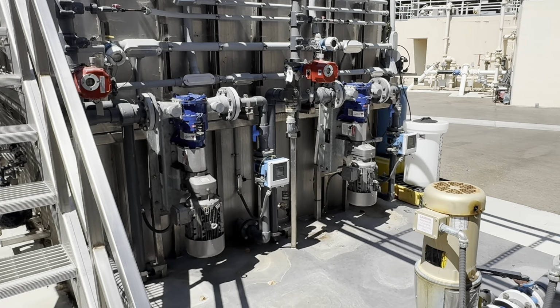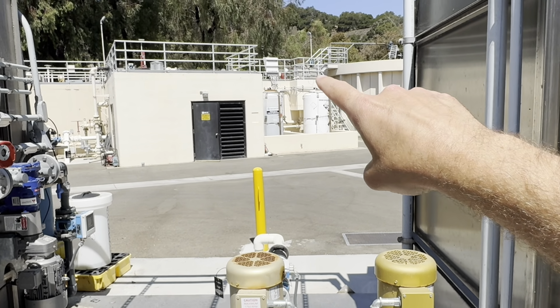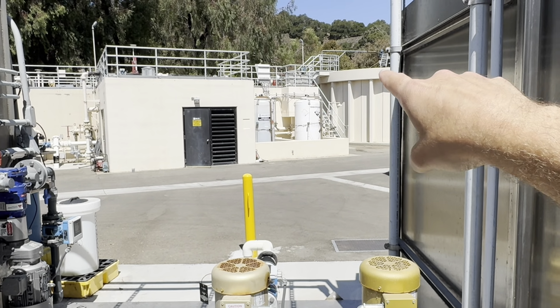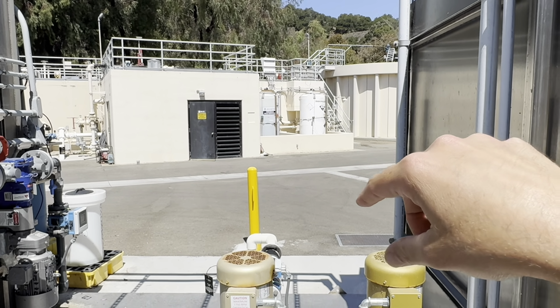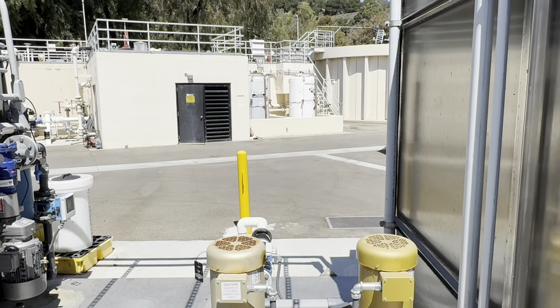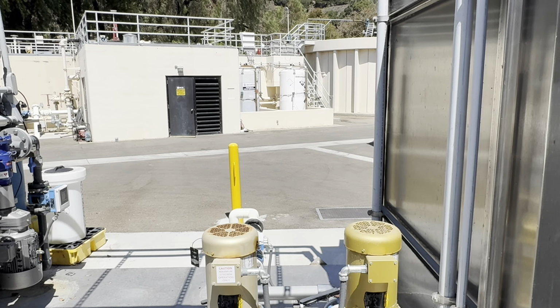Something cool we're working on, like I said, is reclaimed water. And so over there, we actually pump right now to our contact chamber and mix effluents with the trickling filter, but soon a UV skid's going in over there, and we're going to be putting all that in. And you better believe I'm doing a video about that when we've got a UV skid and we can have two different kinds of disinfection here.